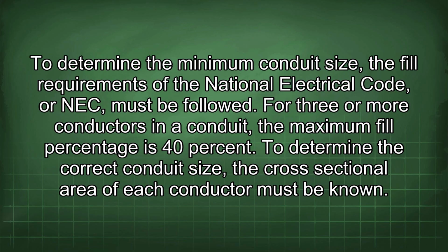To determine the minimum conduit size, the fill requirements of the National Electrical Code, or NEC, must be followed. For 3 or more conductors in a conduit, the maximum fill percentage is 40%. To determine the correct conduit size, the cross-sectional area of each conductor must be known.